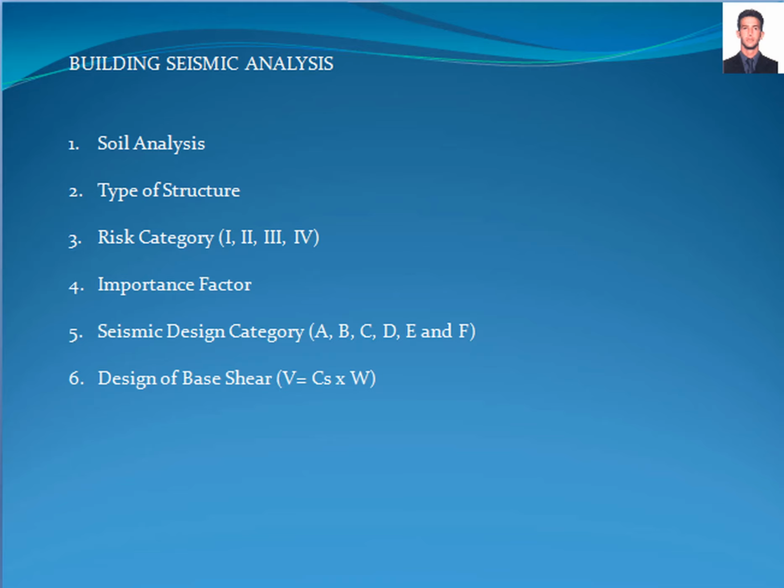In this tutorial, we're going to talk about the seismic analysis for buildings using the Equivalent Lateral Force procedure of the American Society of Civil Engineers Standard. As in any project, the first thing to do is gather the basic information, which is divided in these 6 steps: soil analysis, type of structure, risk category, importance factor, seismic design category, and design of base shear.